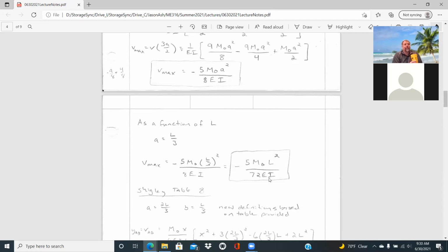Anytime you have continuity for each section of the beam, you have to draw your free body diagram and figure out your internal moment as a function of X. Integrate through, you'll have 3 more equations. So anytime you have a boundary or a load that's applied throughout the beam, it's just going to multiply your number of equations by 3.